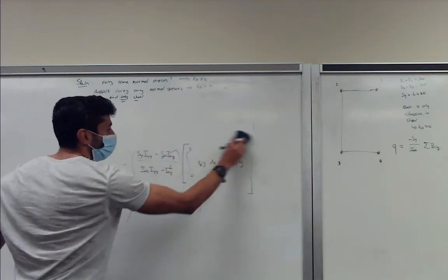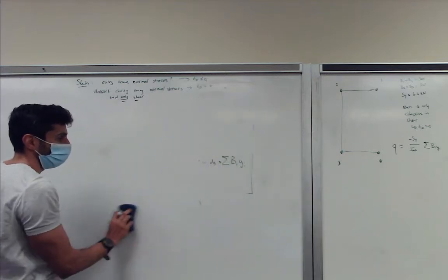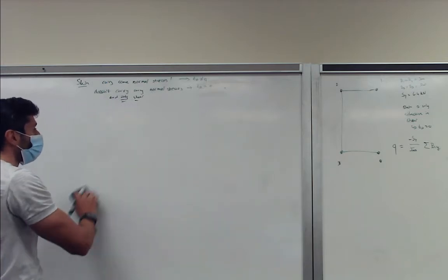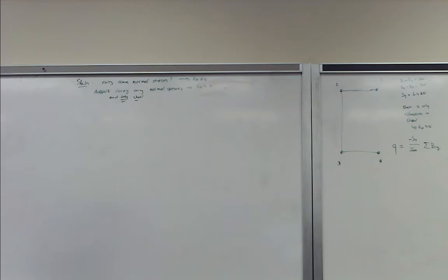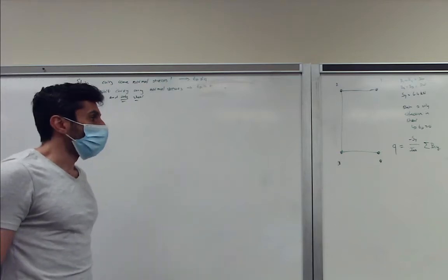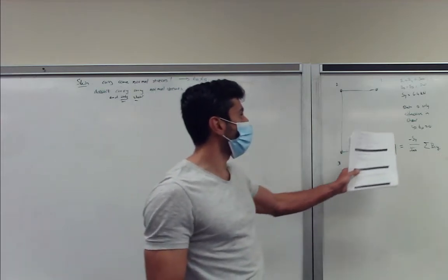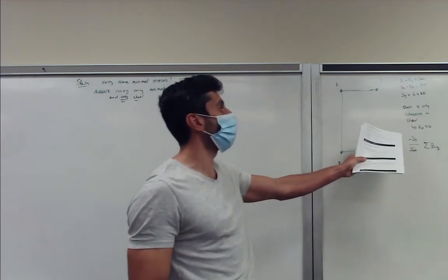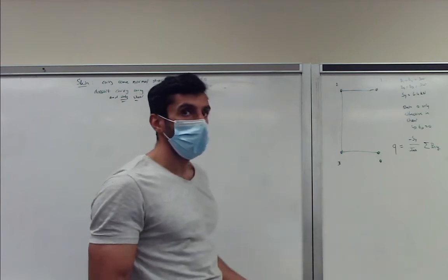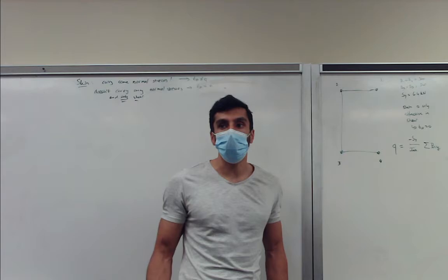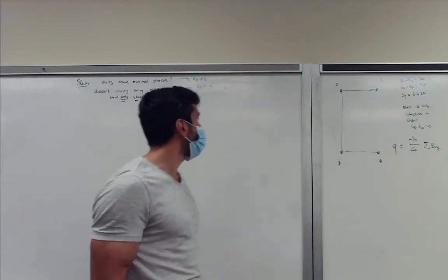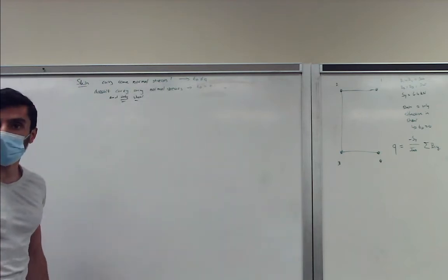Yeah. So these assumptions, are they predefined, or is it up to us to assume whether they carry any stresses or not? It will always be given in the problem. Words like it's only effective in shear. The problem will state the following cross section is only effective in shear. For you, that should be a trigger phrase: only effective in shear, and therefore there are no normal stresses.